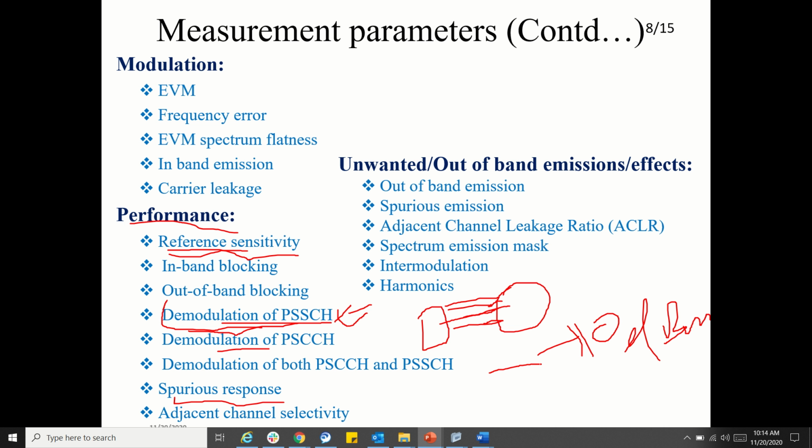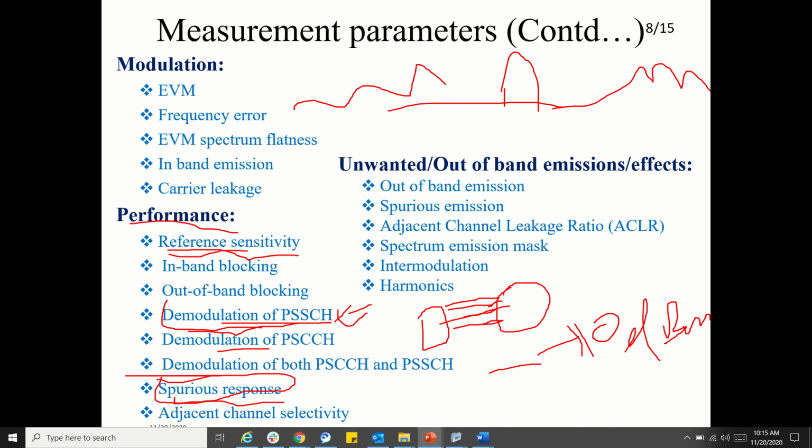If you connect a spectrum analyzer and look at the wide spectrum, you will see a lot of peaks at certain power levels, apart from your desired signal. These may be spurious responses from your devices, because the device also has signal integrity problems.